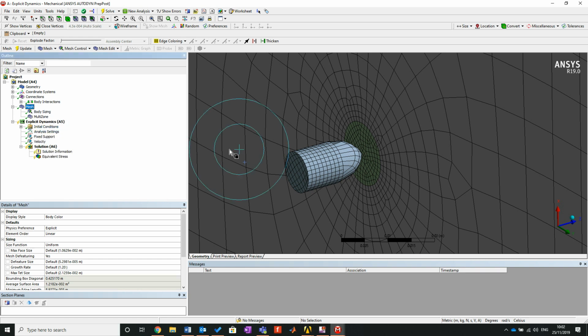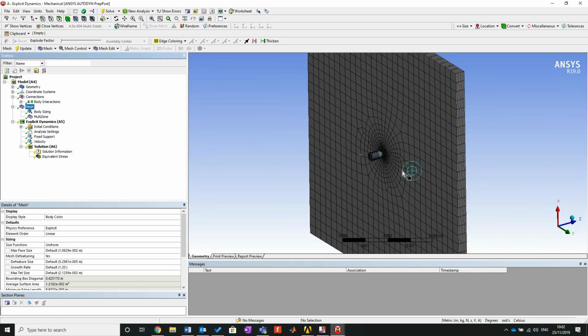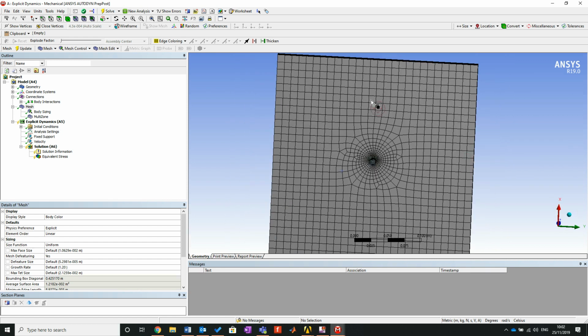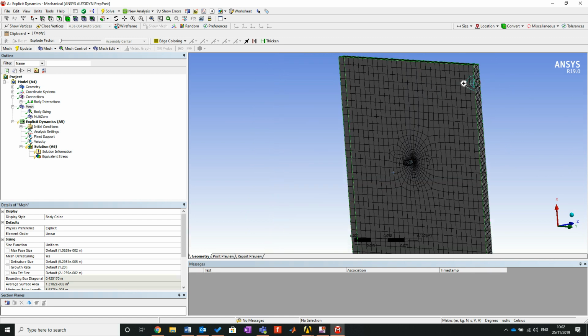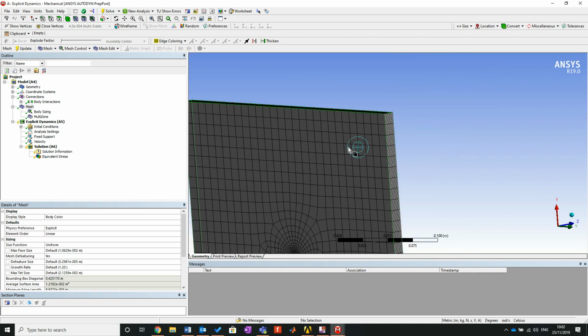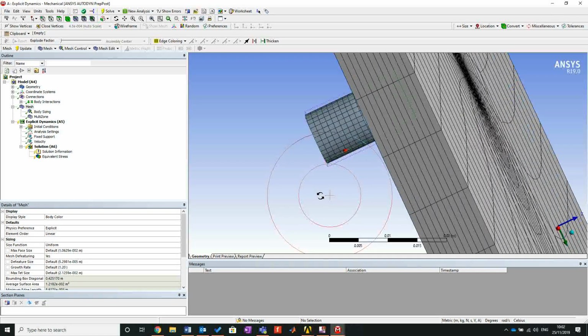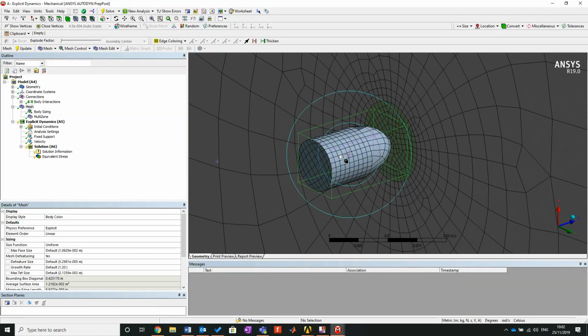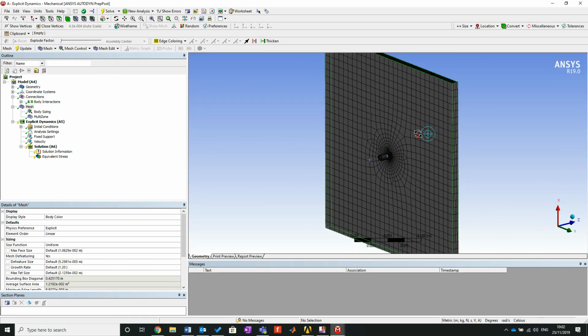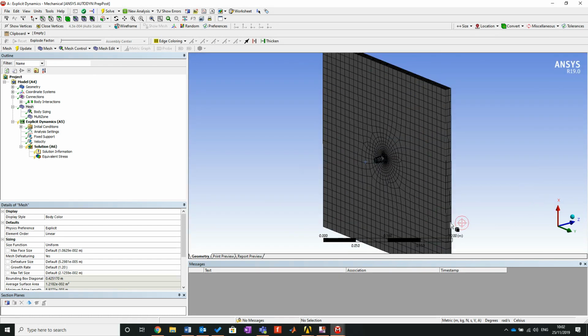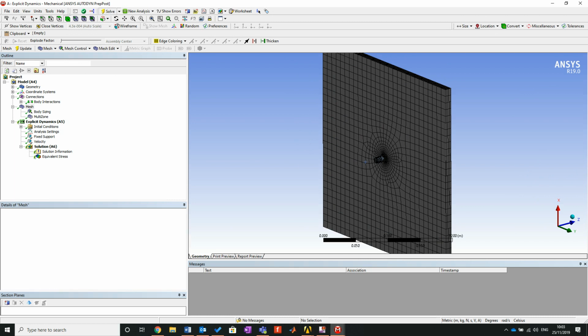And, right click, I'm going to generate mesh. So the mesh is generated. What you'll find now is that where the interactions are across the actual areas here, it's become a lot more uniform. It's what would be expected, the 8-node methodology. However, when we get into here, you'll notice we're at a much tighter meshing procedure. Right, so I'm pretty confident now this will do it. Don't quote me on that, because this might go horribly wrong. So I'm just going to hit run, hit solve and give it another whirl.